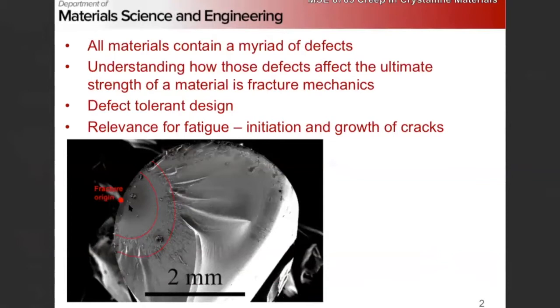A nick in a surface is a material defect in fracture. So we're talking about things that are typically an order of magnitude larger than what we would normally consider a defect. However, that's not necessarily true, right? We talked about how the intersection of twin boundaries gives a stress concentration, and that's a spot where cracks can nucleate from, because you don't have complete degrees of freedom with respect to deformation there.